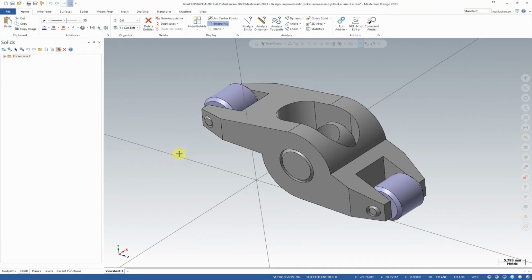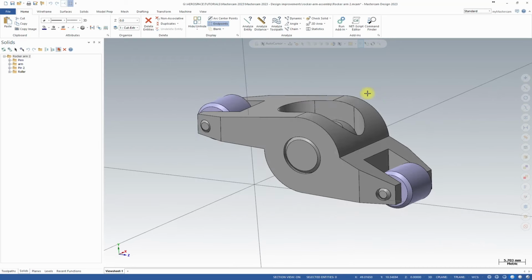And instead of having all 3D models listed in one long list, you can group them together and put them in folders. So at the moment, I loaded the SolidWorks file, and as you see, I've got two rollers, and Mastercam created the group or the folder, and those two rollers are in this one folder. And I didn't have to create those groups myself. Mastercam created those groups automatically, and Mastercam will create those folders for every assembly that you open in Mastercam 2023. Our assembly here is very simple, but you can see how things are well organized. In this group we also have 2 pins.